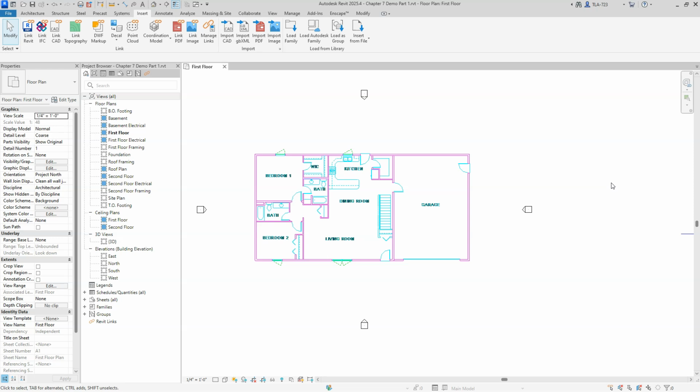They're really important because you can pin them in place and then lock and align your model to those reference planes. No matter where you are vertically within your model, you can know that you're always lined up in the right spot. You'll always see those reference planes at any level, whether you're down in the foundation or up at the roof. So let's go ahead and create those reference planes first.